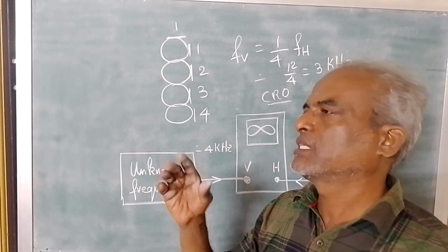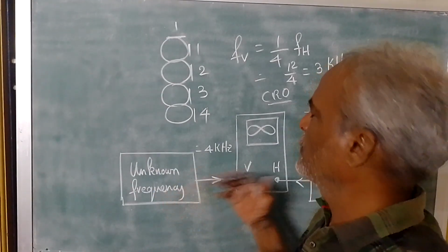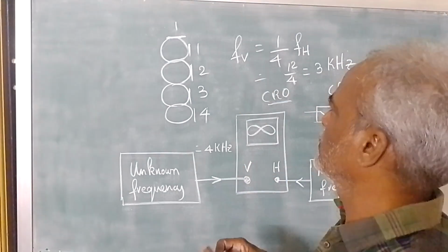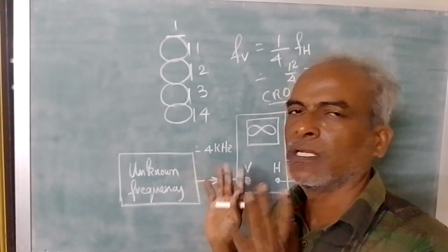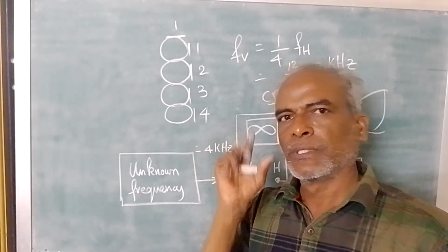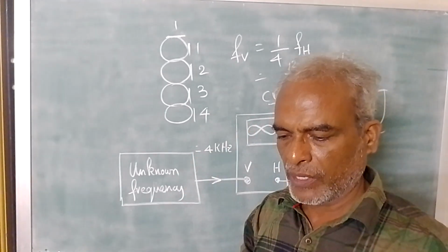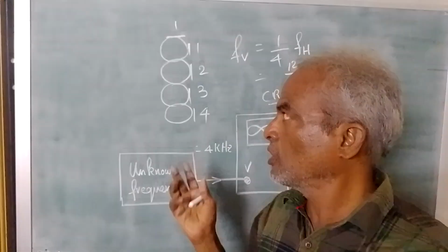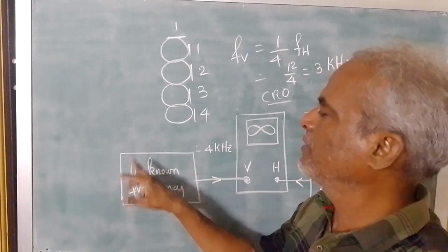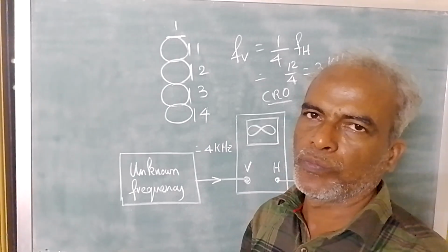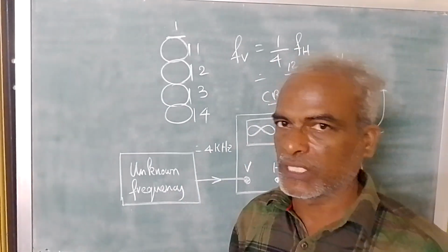So you fine tune and see the readings and check whether the unknown frequency, whatever answer you get for this case, say you should get 3 kilohertz. Yes, it's 3 kilohertz is showing in the signal function generator in the sinusoidal mode. That's all about actually the function generator, the output will be very small. That is not going to affect your CRO.